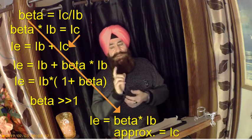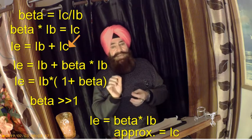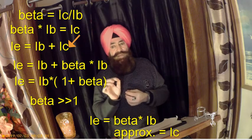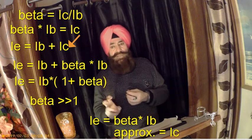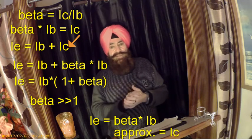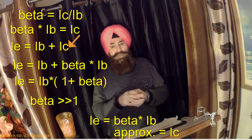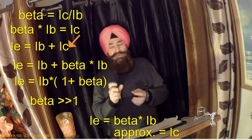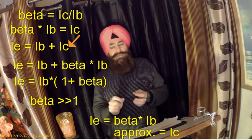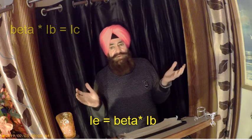One thing keep in mind, IC will be slightly less than IE, and that depends upon the value of IB. So these are the basic equations to remember. It is called a current controlled device. Bipolar means electron and hole are responsible. The base emitter voltage, when the transistor is in the on state, remains close to 0.7 volt. And this is all. Thank you very much.